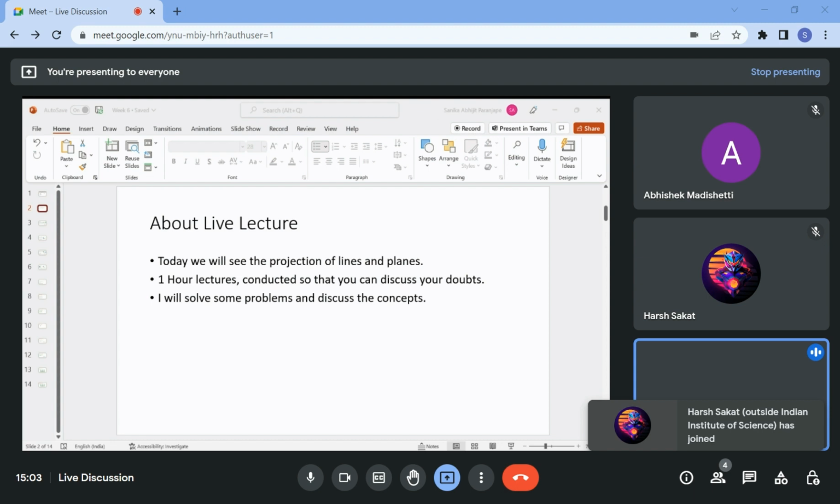Now what they have told is line AB is 20 mm long. So 20 mm is the true length of this line, and we have the true angles. So now what is the true angle with respect to HP? True angle with respect to HP is equal to 30 degrees. So I have 30 degrees with respect to HP and I have the true length. So with this, I can only get the locus of point B.